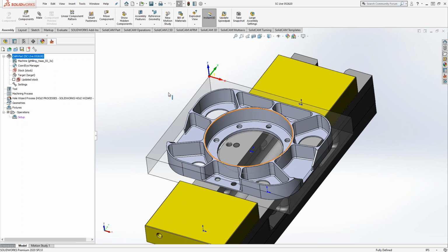So I may do it a little bit different than what Mark does, and we may do it different than how you guys would. So we're just going to show you how maybe Mark and I would approach this part. But me personally, I would start off with a 3D machine. I would as well, especially even if there's material on the top. You notice that at the end, this thing's not going to have any top face there anyway. So there really is no point in wasting time going back and forth and facing that when we can probably just finish those rib tops later with a profile or something like that. So I wouldn't waste time removing any material that's just going to be roughed out anyway. So 3D machining would be the thing I start with.